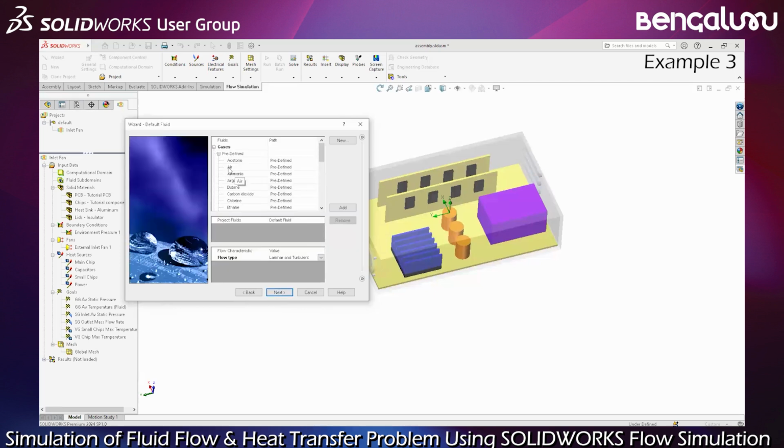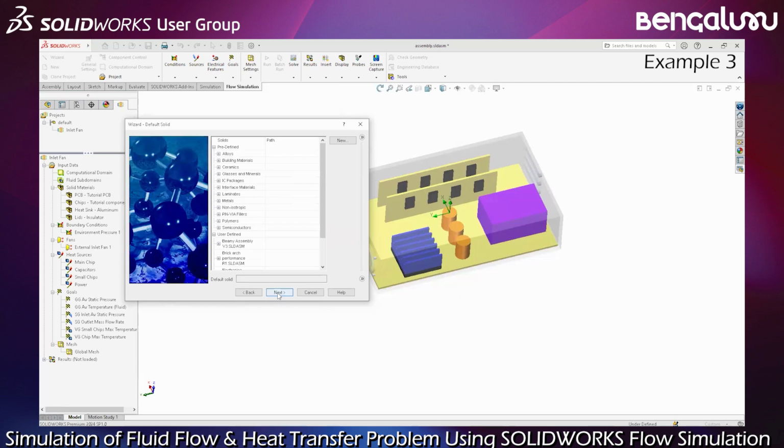Usually, I just have the air as the fluid, the gas here. I don't need that. Usually, this is what is used for electronics cooling. And the rest is more or less default, except I have to use here, I know that they have maybe 5 groups of material: the enclosure, the different chips, the different components, etc. So here, I'm just going to select the default one.